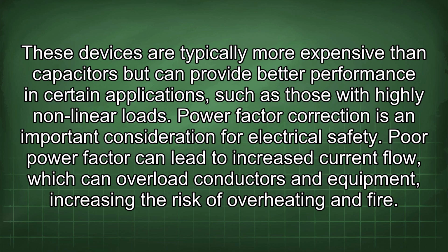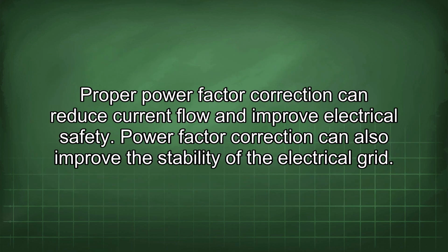Power factor correction is an important consideration for electrical safety. Poor power factor can lead to increased current flow, which can overload conductors and equipment, increasing the risk of overheating and fire. Proper power factor correction can reduce current flow and improve electrical safety.